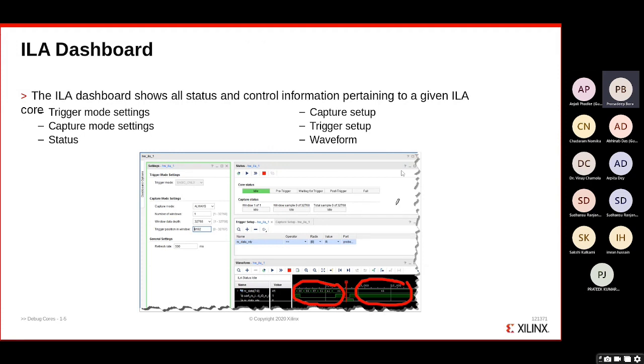You can see, depending upon the trigger condition, we can capture the data. So these are the main differences that we need to follow. Now, in your case, let's say I'm implementing a FIR filter. I'm giving a more basic example: I'm applying a shift register. I want to see the shift register code, and I want to see each and every bit shifting stage by stage. So that's why I will be using ILA.